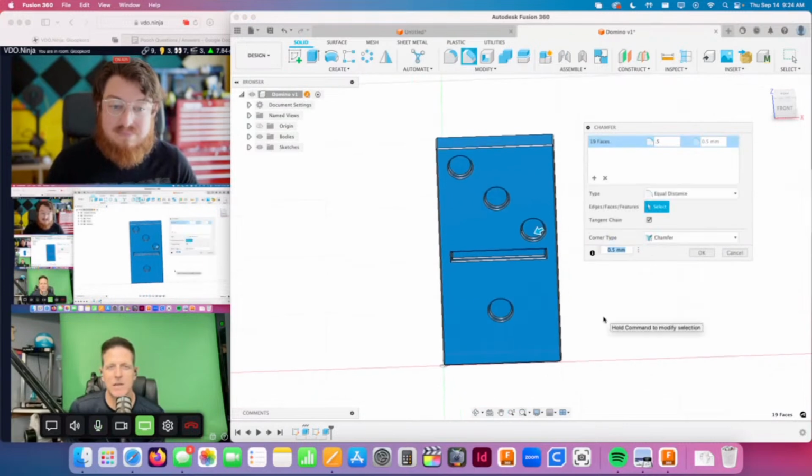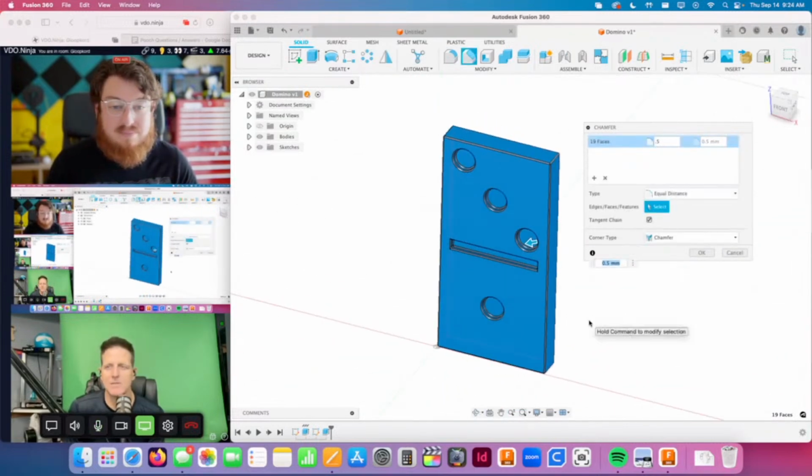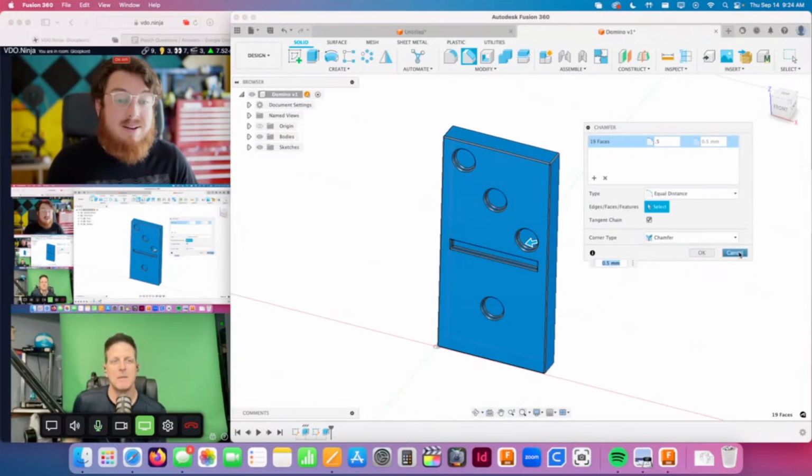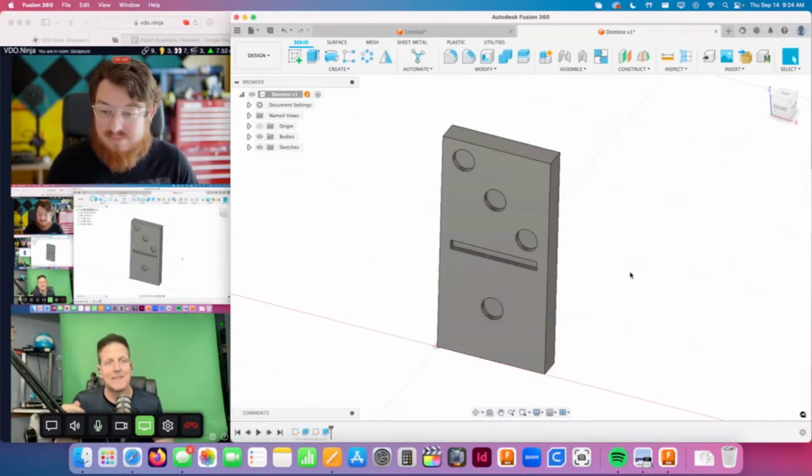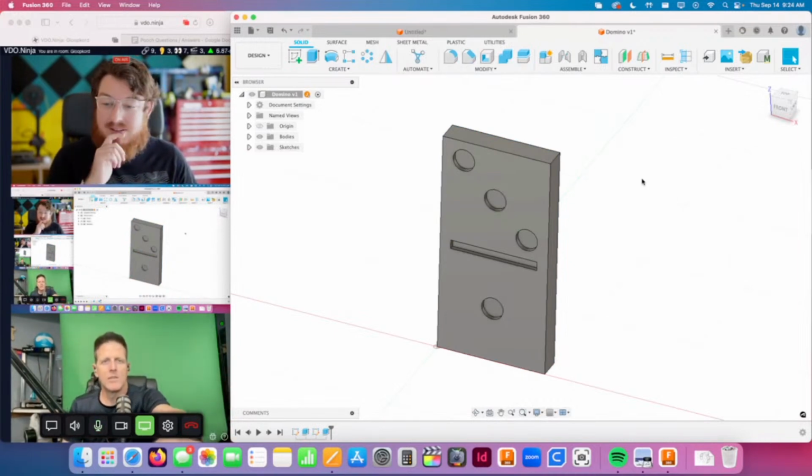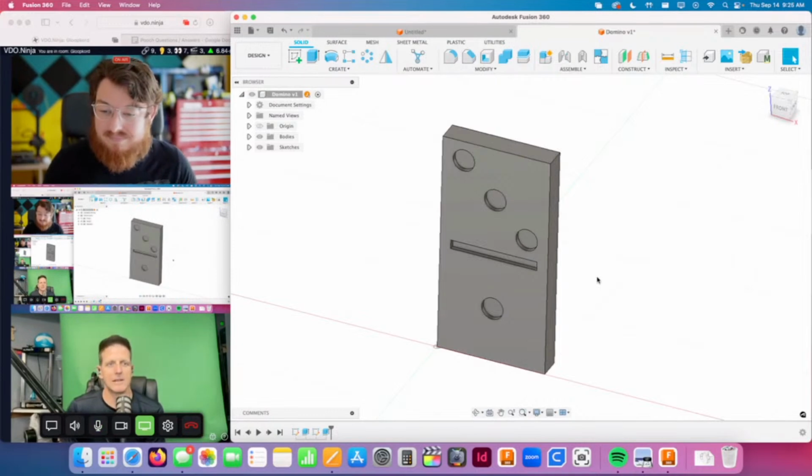So it's the selecting of the entire body, and maybe it's even better. This is where your selection foo becomes critical, because maybe you're better off selecting the entire body and then deselecting the components that you don't want chamfered. So for example, the dots, maybe you don't want to chamfer the actual parts of the dots. As a speedy mechanism, you could select the whole body and then hold down Control and deselect. Okay, absolutely. All right, he can be taught.